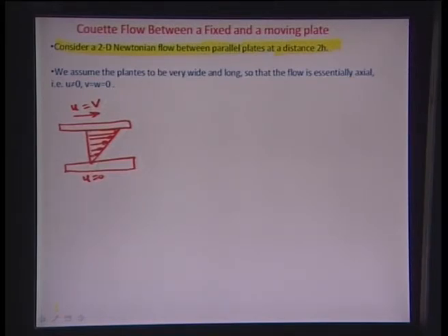So you have a zone of no slip here, and you have a zone of no slip here. You can assume that this zone of no slip leads the fluid layer to move integrally as one part with the plate, and this other zone of no slip kind of rests it back, and a velocity gradient is obtained. Let us assume this to be u(y), as a function of y, where y varies between plus h and minus h. We place the coordinate system so that the origin is in the middle, between the plates.